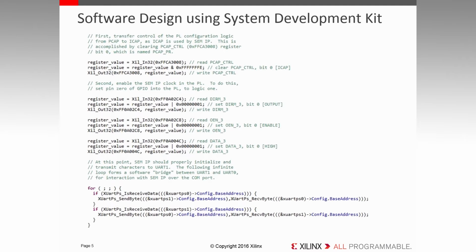Once the UltraScale architecture SEM IP has transitioned to observation state, it only transmits messages in two scenarios: a reply to a command you sent, or a notification of an exceptional condition. Given the exceptionally low SEU FIT of UltraScale Plus devices, virtually all of the time, you simply listen. Let the UART do the listening for you, and upon interrupt, have your interrupt handler inspect the notification for as much information as you care to have and relay it to your system management software.